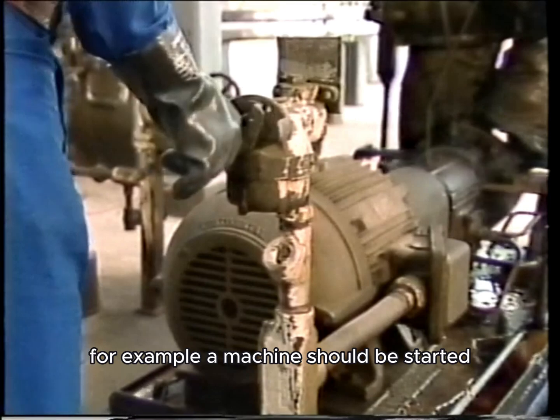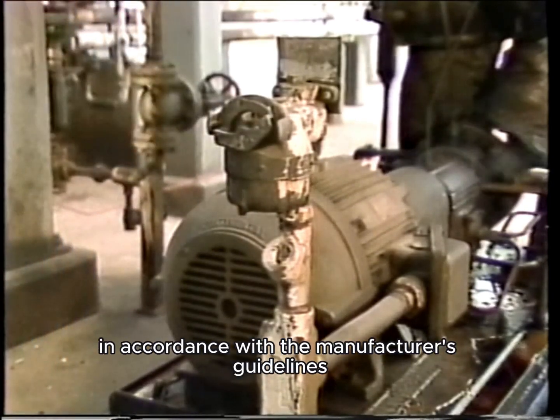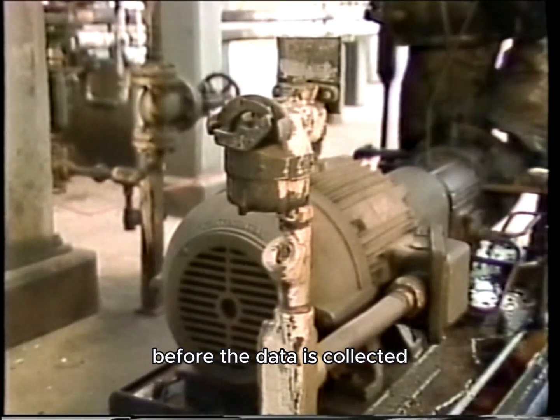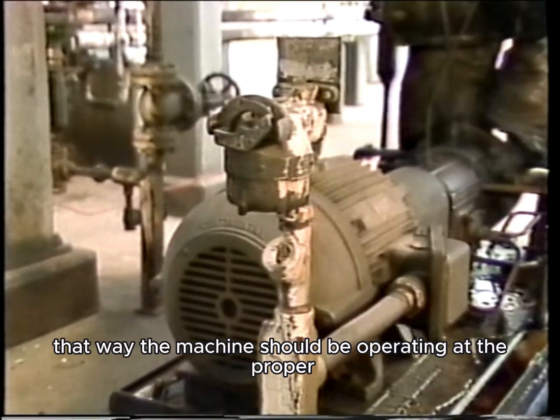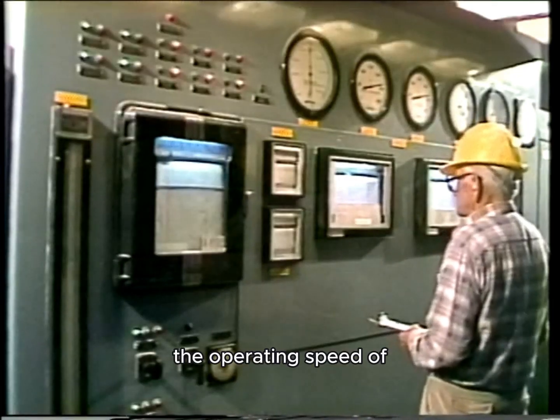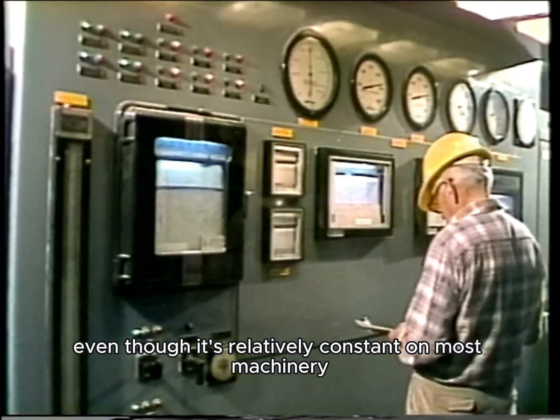For example, a machine should be started in accordance with the manufacturer's guidelines or company procedures, and given sufficient time to warm up before the data is collected. That way, the machine should be operating at the proper speed and temperature. The operating speed of the machinery is normally checked, even though it's relatively constant on most machinery.